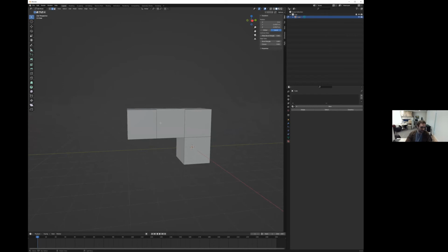I will be adding an edge loop. So now that we're talking about edge loops, here's an edge loop here. Say I wanted an edge loop right in the middle. Edge loops are pretty common, and you'll see why as we create the cup. So if I press Control R, and you have to be in edit mode for this, you can place an edge loop here.